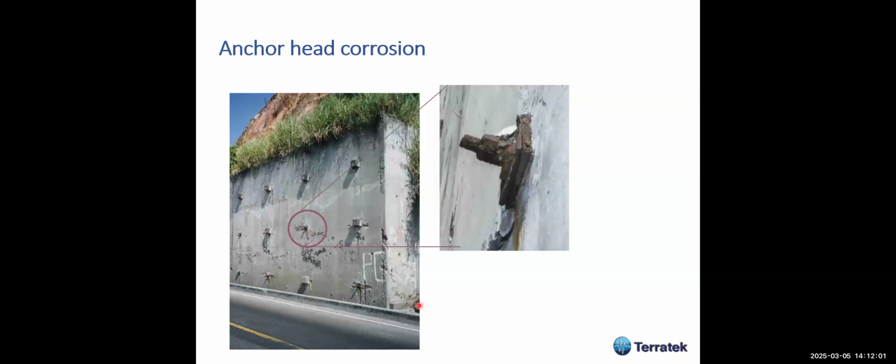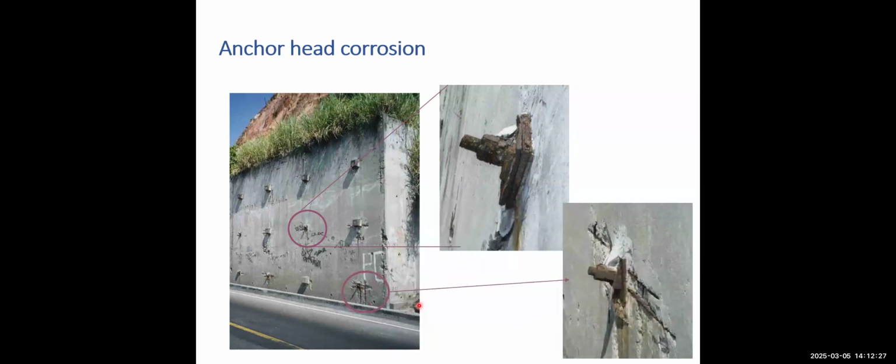And then the corrosion rate in this case was very important. The corrosion makes the steel expand a little bit, and then the protection fell off, as you see here. This has been repaired already some 10 years ago. This picture is from about 15 years ago, and about 10 years ago it was repaired. As we see here, the rebar is exposed, and this is very bad, of course, and you have to do maintenance.